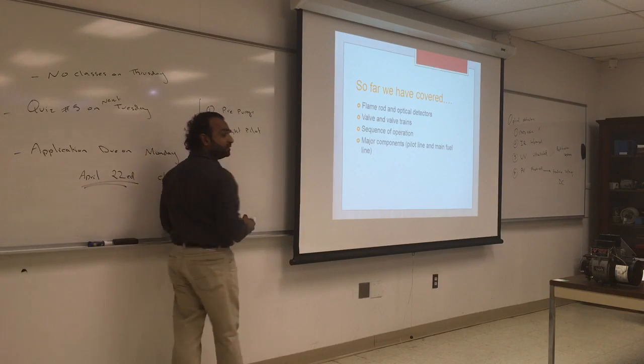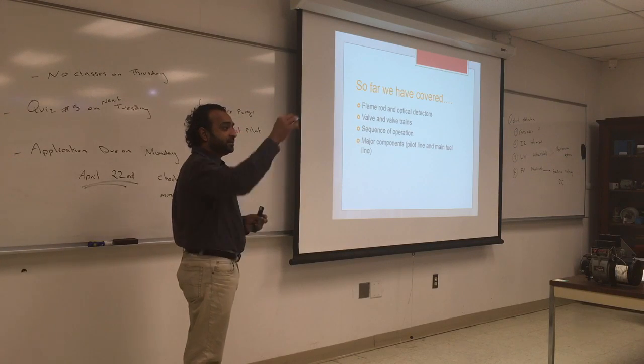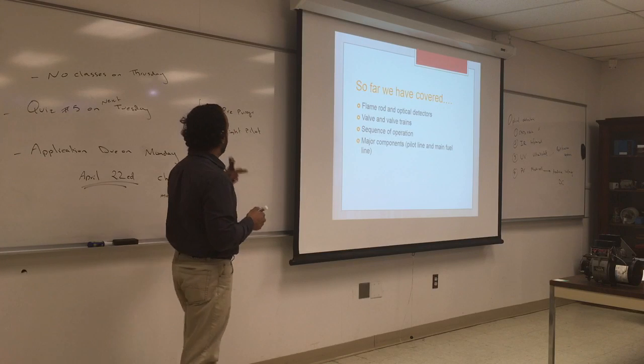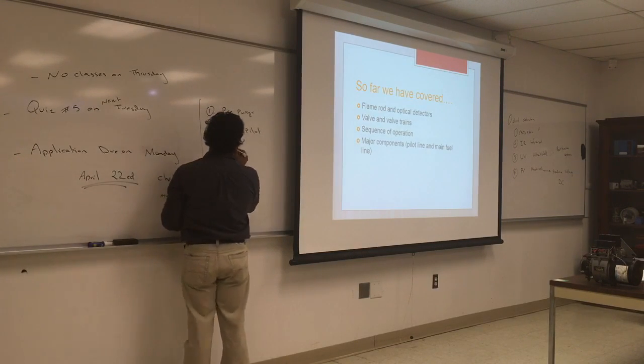Wait, Father, these five steps do what? Just to check on a burner? No, this is the operation that happens in the main operation. Oh, okay. Yeah, when you turn it on, this is what happens. First, you'll pre-purge, light the pilot, prove the pilot.